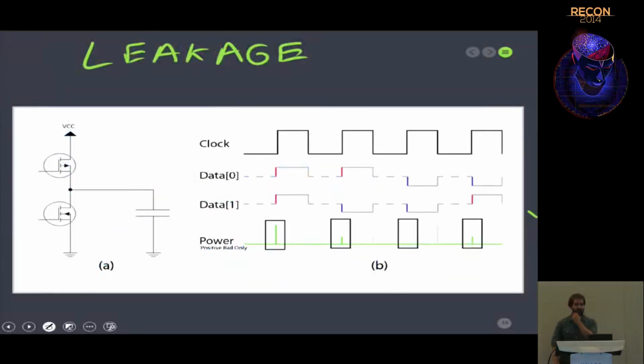So it uses this pretty basic idea, and that's that if we have a digital device, inside the digital device, aka a chip, there's going to be different modules. The ALU might go to registers or something like that. And in between them, there's the data bus that the data goes across. Each of those lines of the data bus is basically a capacitor that, to set it high or low, you're driving it to 1 or 0.